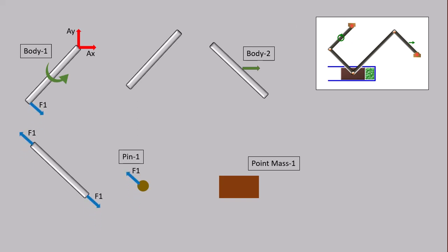The first inclined 2-force member, the second 2-force member, this is the complex pin where we have 2 2-force members and the piston. So Cx, Cy is the interaction between the complex pin and the piston.